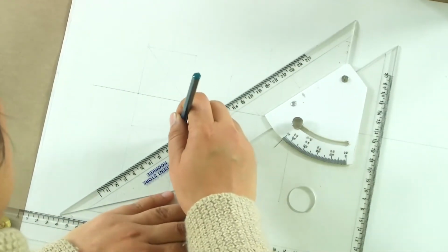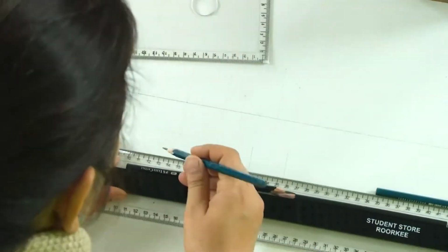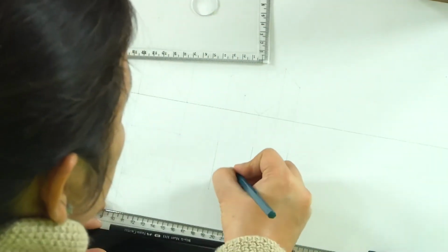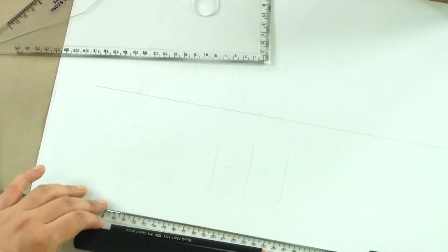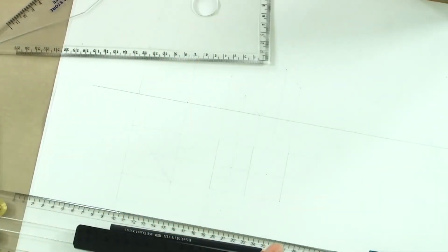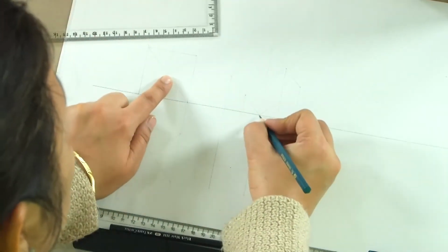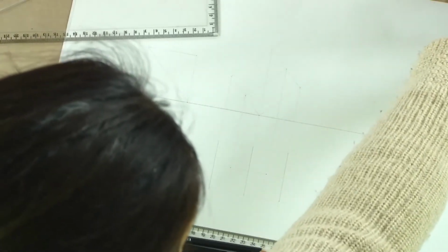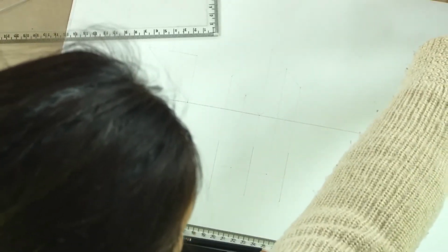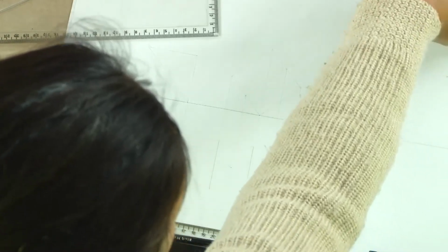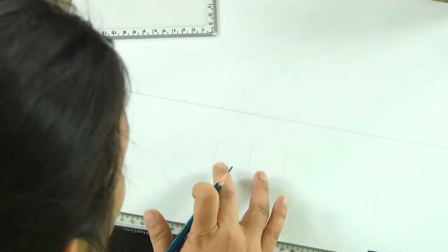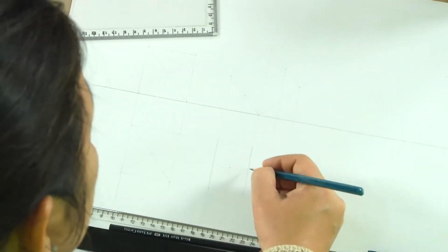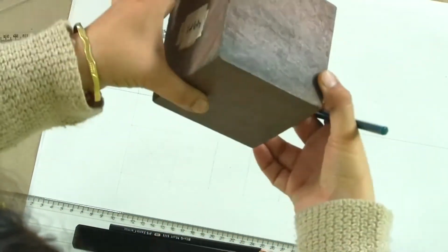If we locate the position of the axis, then this is our axis. So the axis has now diminished, and also remember that the point of rotation is this point, and it is actually an edge. This entire cube is going to rotate about this edge. And now when we further say that this is rotating another 30 degrees, making an angle of 30 degrees with the VP, we are talking about the axis, but it will be rotating about, say, this point, which is the midpoint of this. So this entire thing will be rotating.